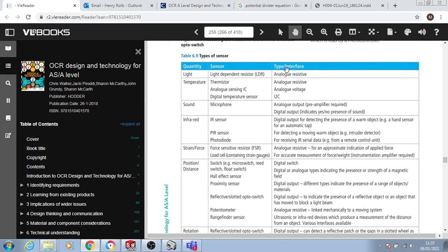And the ones that change the resistance are going to use a potential divider to be able to control an input voltage. You might have a sensor that's got a minuscule voltage just generated, something like a thermocouple, which is another heat sensor. Just when it gets really, really hot, you get tiny voltages out of a twisted wire of different types of metals. And in that case, you might want to use an amplifier or 2 amplifiers or 2 transistors in series just to amplify that circuit, but we'll cover that in a different video.